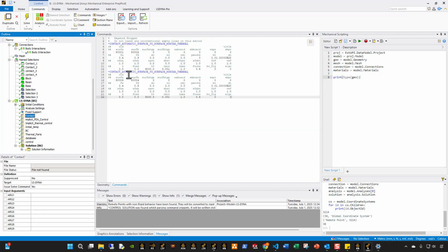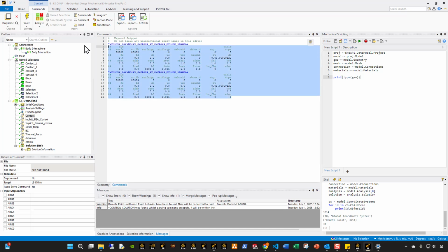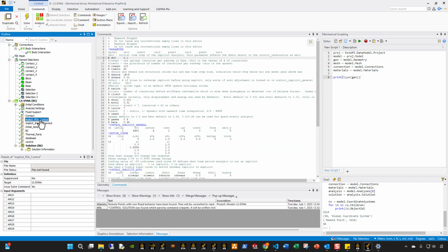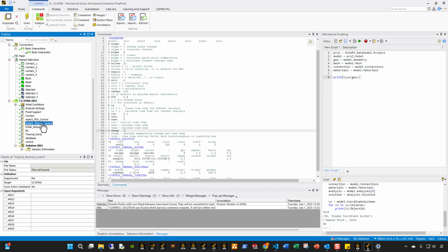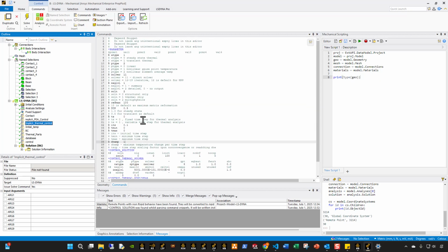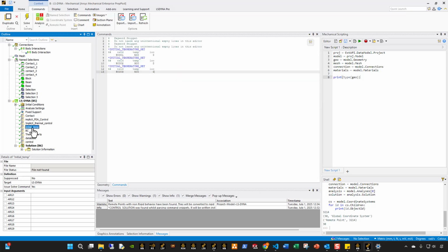So if you look at everything I did, this is the thermal contact pair, right? This is my conduction, this is my minimum maximum gap, and then that's essentially a thermomechanical contact pair. It's an automatic surface-to-surface contact, which is essentially like a frictional contact. That's also a thermal contact. So that contact pair, this single contact card, can transmit heat through conduction. It can also act like a mechanical contact, right? So it's a really awesome feature they've created. These are the most powerful, important things you want to fine tune to get the problem to solve correctly.